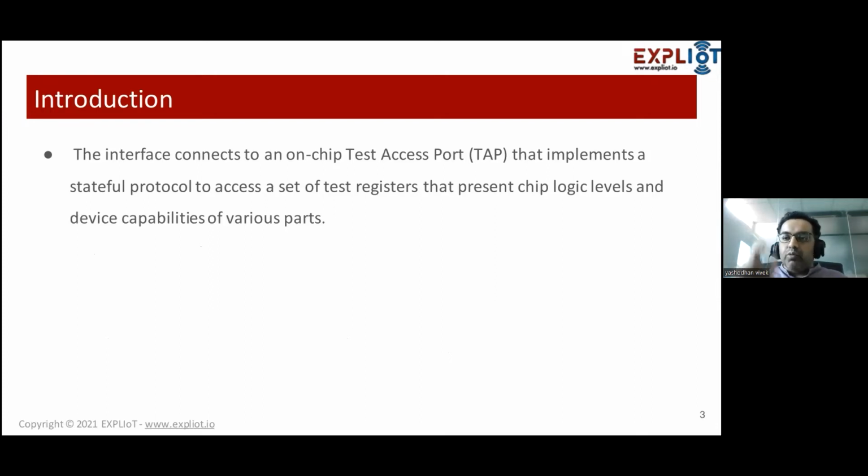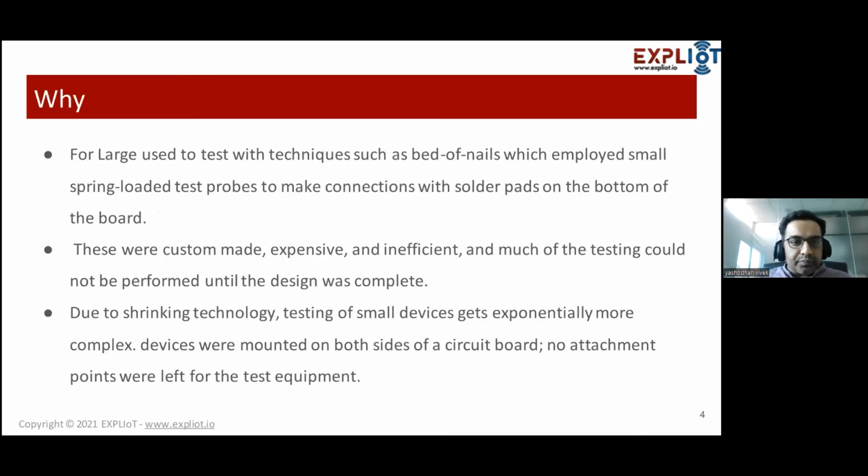And the most important thing, it's a stateful protocol, meaning it has implemented a finite state machine over there. So state by state, bit by bit, we are basically trying to decode or debug what is there. So it is not exactly similar to what we do in software debugging. It is a bit different when we go to the actual JTAG debugging part.